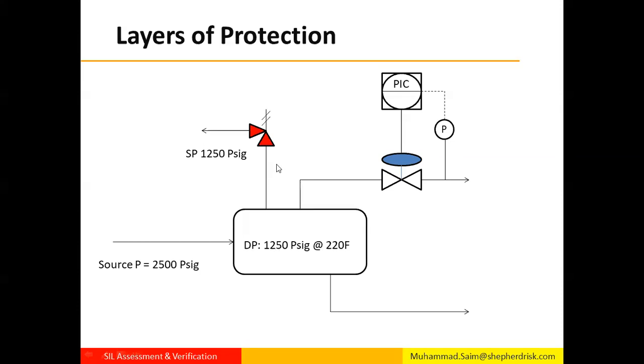Our process hazard analysis highlighted a scenario that if there is a blocked outlet of the gas stream, the vessel will be subject to an overpressure of 2.5 times its design pressure, which is enough to rupture the vessel, consequently leading to fires or toxic releases.